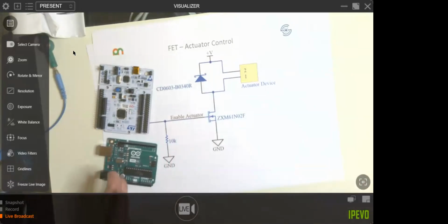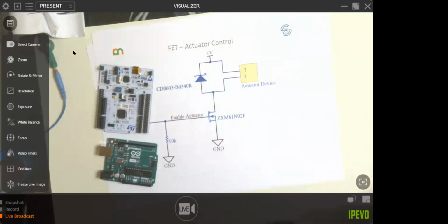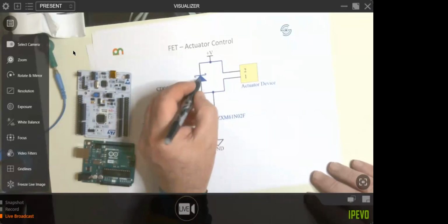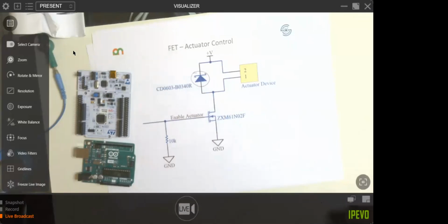So once again, just use a transistor to switch on and off the, let's say it is a haptic motor, a tiny motor with a little weight on the end, so you feel the vibration. And just another top tip, if you do that, don't forget to put a reverse diode into the circuit.